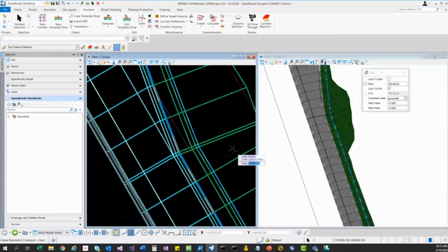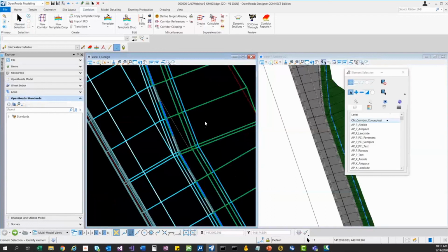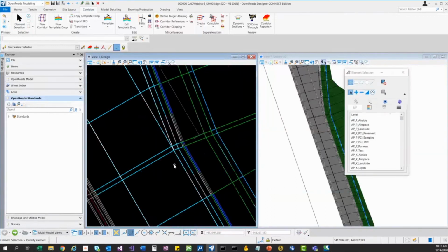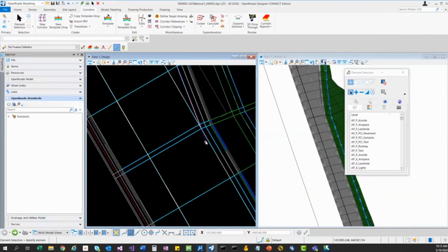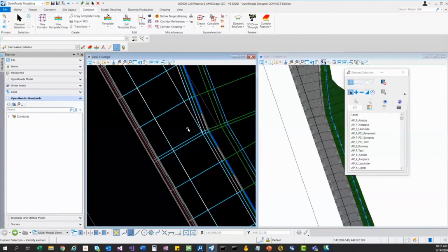Another thing I wanted to show was a key station. It's real simple. When I added that parametric constraint, it added that drop location or processing location right at that point. But what if I didn't have that and I needed it to calculate something right there to make it nice and neat? You can do that just by adding a key station.